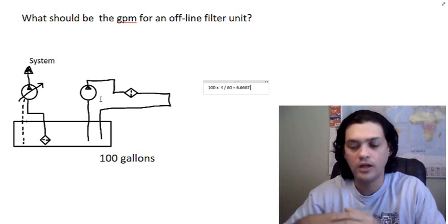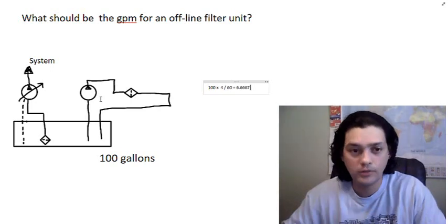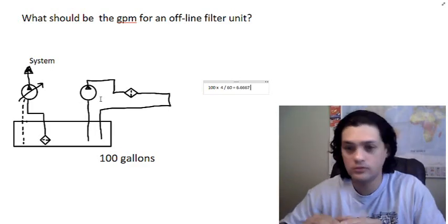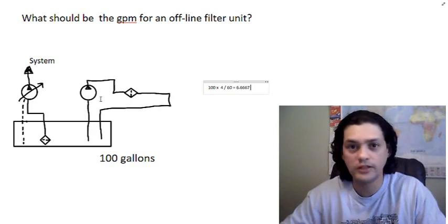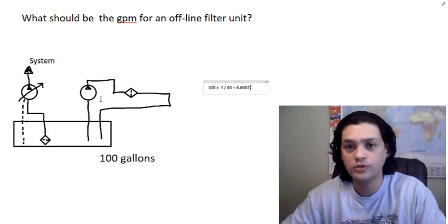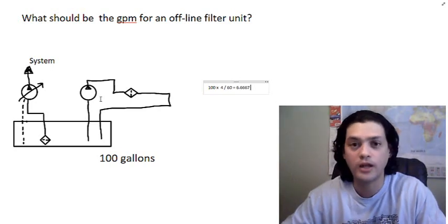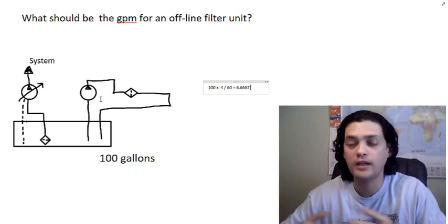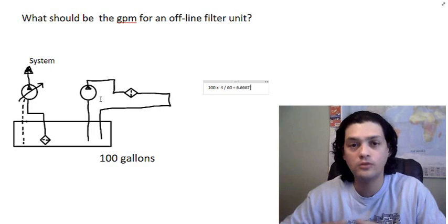So when you install a machine and you keep an ISO 4406 contamination level proper to the hydraulic system, to the right levels, you'll see a lot less failure in the system. A lot of people get surprised. They say, wow, I put this one, I left it there, and I'm having a lot fewer failures in the system, a lot less leakage, and a lot fewer headaches. So if you're going to invest in an offline filtration unit, leave it in the machine, don't move it.